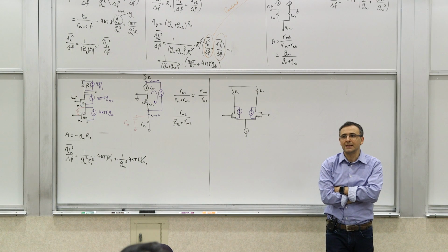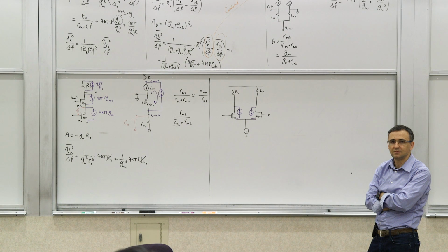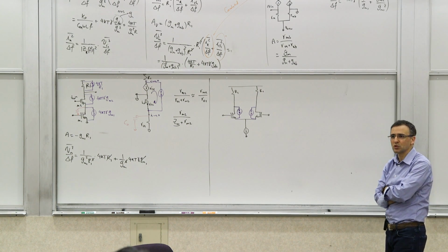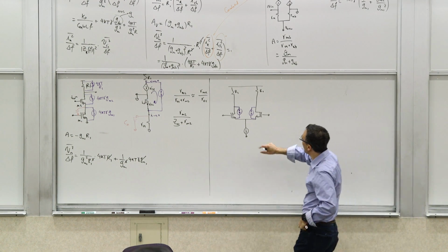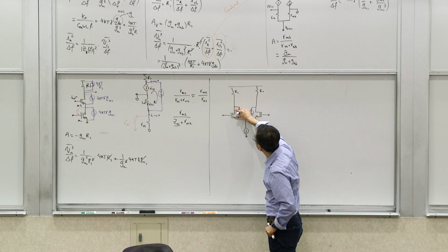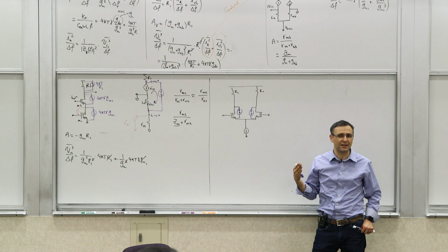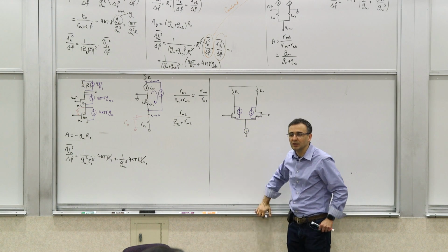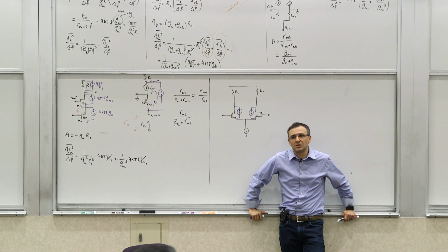So in that sense, what can you do in terms of finding the transfer function for each one of them? What we're trying to see is what's the equivalent input-referred voltage noise, for example. What noise source should I put at the differential input of this thing? So the question is, what is the transfer function from this current to the differential output? You can use superposition, though, right? Because they are uncorrelated, you can calculate the power effect of each one of them. So let's say this noise source was not there. If you had one noise source here, what would get to the output? So think about it. What fraction of the noise gets to the output?